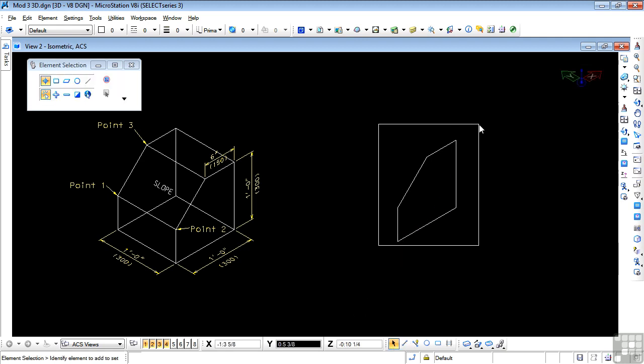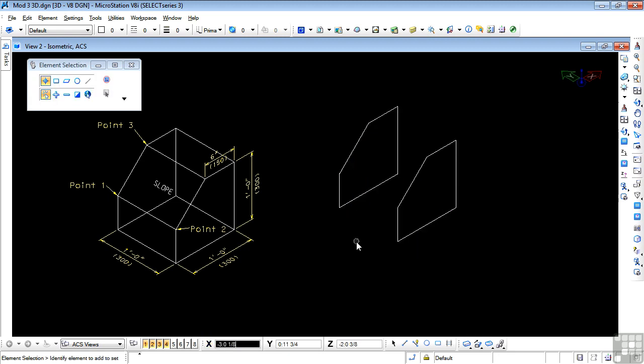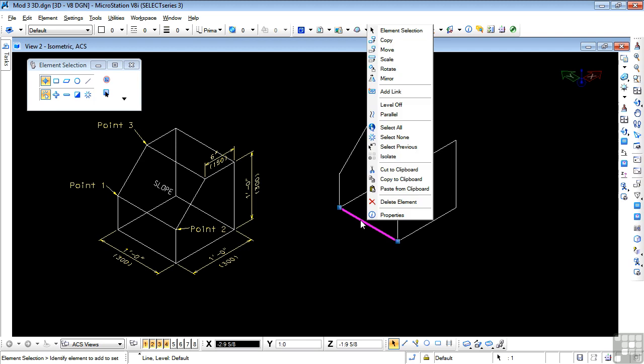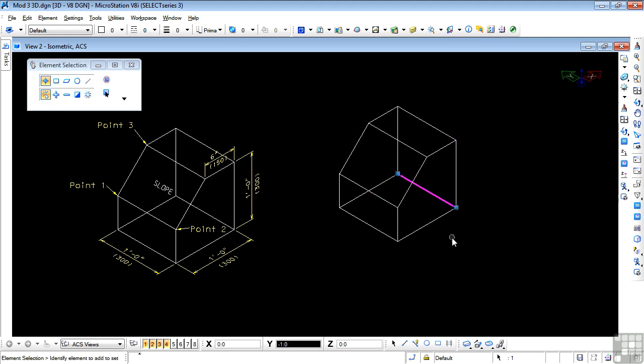I'm going to make a copy of the front face. I'm going to copy that this way by 1 foot. And E to rotate the compass, so I can copy in the correct direction. And that's a 1 foot distance. Left click, and there's my copy. Now we'll do the intermediate lines. There's the first line. I could draw each line itself, but I'm just going to copy this one, which is a little quicker. There we go, all copied.